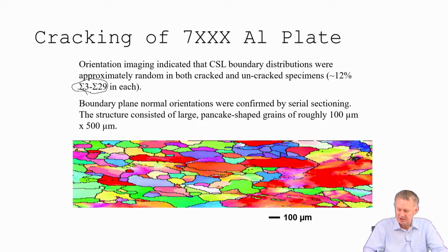So your grain boundaries are largely lying in the plane of the rolled plate, right? So most of your grain boundary normals are in this direction. Certainly the ones that are cracking, if I have my hole expansion here and we get a crack that shoots off on the boundary, then you can see the boundary is always going to be normal to the plate like that.